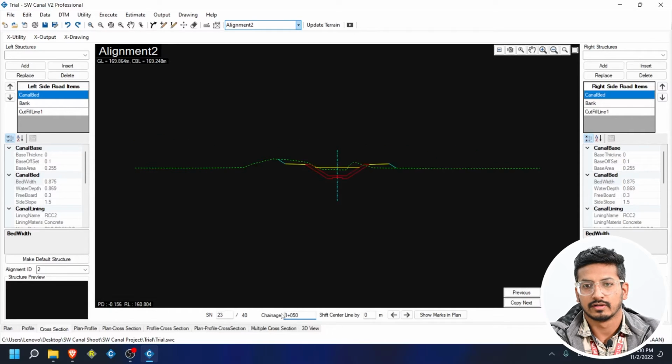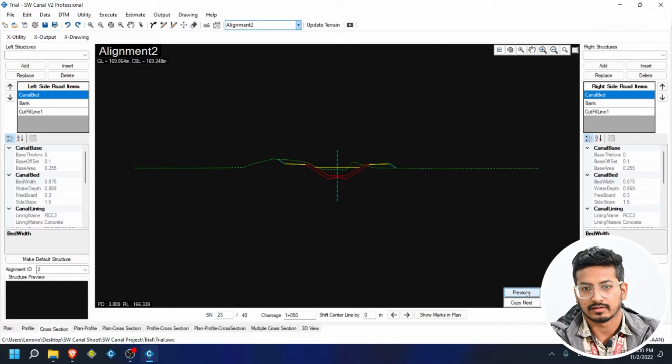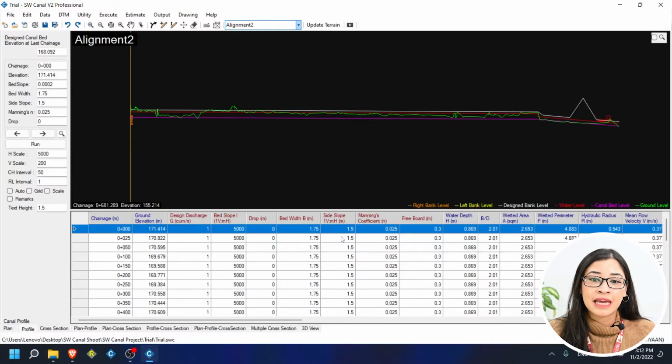In this way, we can give continuous or step lining, but generally the continuous lining is given for trapezoidal canals and step can be given to rectangular sections. Moving on, we will learn how to put in cover slab and mesh, which can be geotextile, wire mesh, etc. We need to keep in mind that the cover slab is generally considered for rectangular canals and wing is considered for trapezoidal canals. We will now make a rectangular canal so that we can demonstrate further.